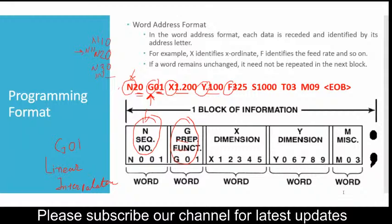Linear interpolation means that I will be defining the feed. So here you can refer to this 325, which is preceded by F. That is a feed function. So this machine will be operated at a feed rate of 325 mm per minute. The machine will be operated at 325 mm per minute.